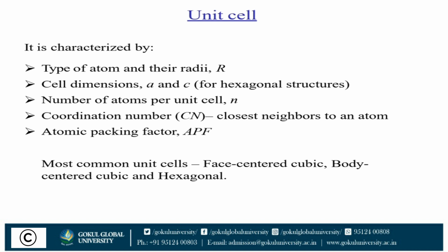All solid metals like iron, copper, and aluminum are crystalline solids. The definite order, manner, and form of atoms producing a geometric shape or aggregate is called a space lattice or crystal lattice. A crystal is composed of unit cells. A unit cell is defined as the contents of the smallest number of atoms which, when taken together, have all the properties of the crystal of the particular metal. The unit cells are arranged like building blocks in a crystal. That means they have the same orientation and the similar faces are parallel.